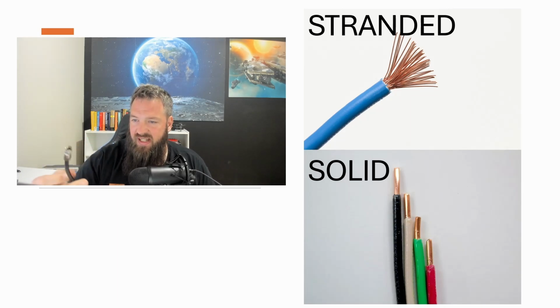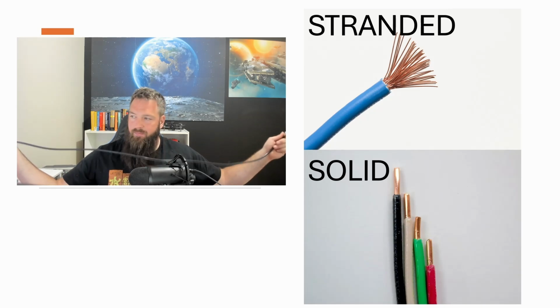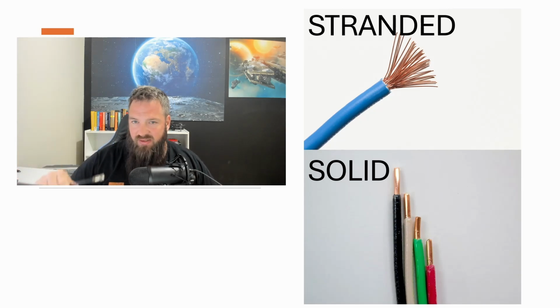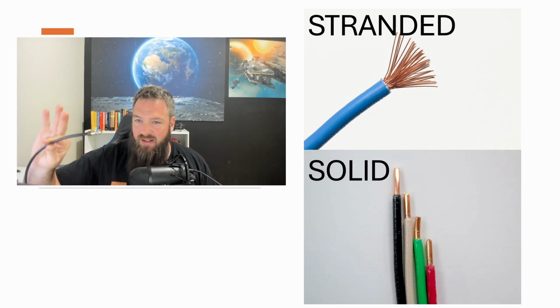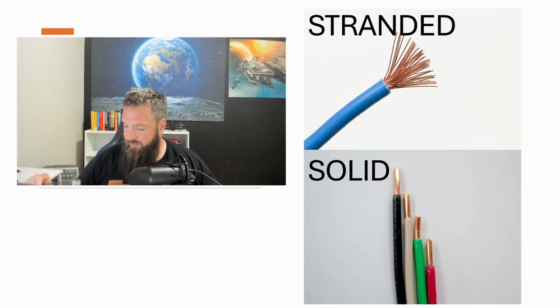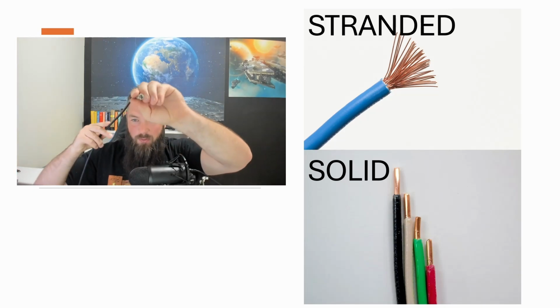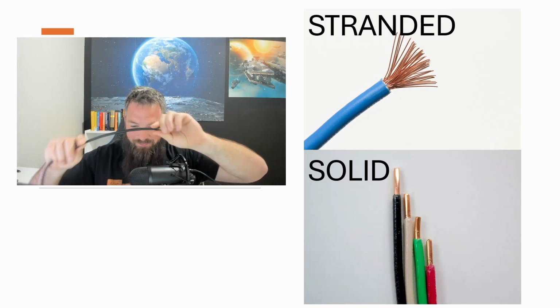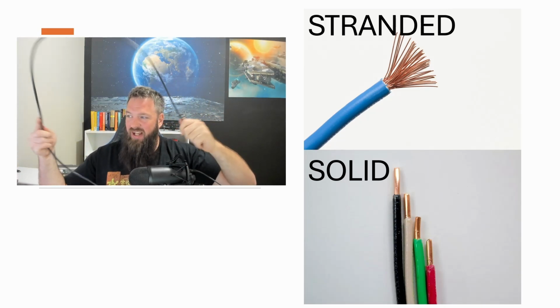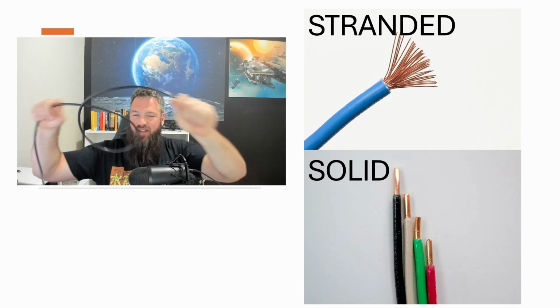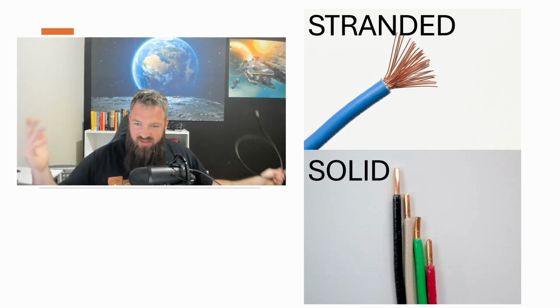It's designed to have 50 ohms of impedance throughout the whole entire wire. So when you terminate this, there's no power loss and you don't have echoes. This stuff matters for applications like this. This is also one little tiny wire with a thick cable. It's not flexible. It has some flexibility, but it's the use case that it's there for. If you go through and you have audio, solid cable will give you the best sound.